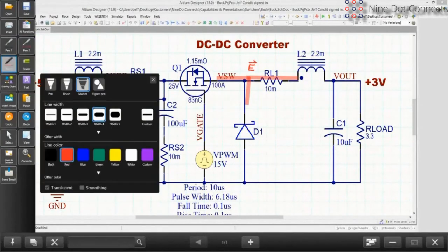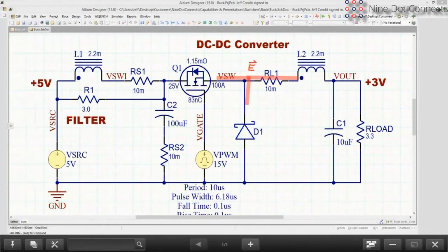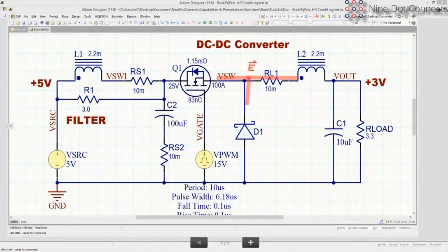There is another node that is very important, and that is where the current switches instead of the voltage. Notice that some of the time, the inductor in the output is going to keep the current flowing through the diode, and some of the time it's going to be flowing out of the capacitor. The ground from the bottom of the diode over and up through the capacitor forms the other part of the loop. So this is the current loop where current is going to be changing.